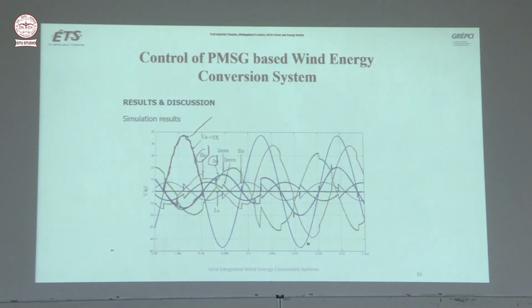It means it is not a load, it is the current power generated and pushed into the grid. Okay, and this is the load current, and the green is the inverter current. Why is it non-linear? Because it is taking care of the harmonics. So it is cancelling all the harmonics, plus it is giving the fundamental component of the current.